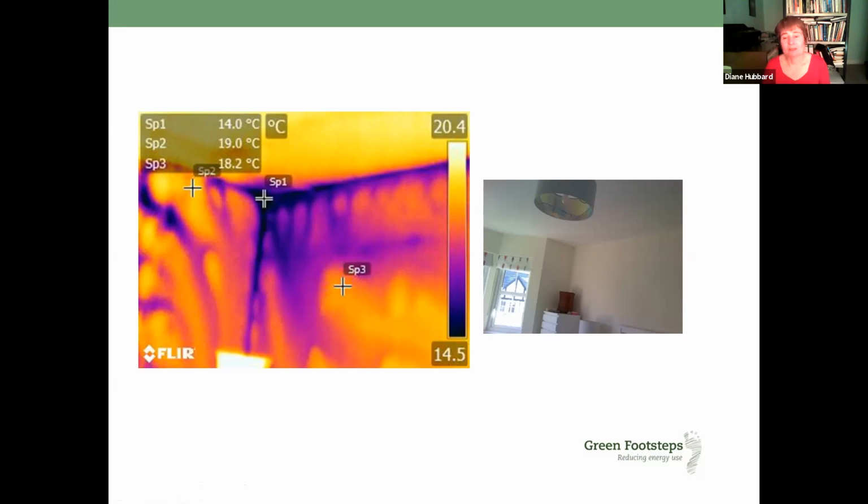And plasterboard should be edge sealed, so around the perimeter of each board as it's fitted, it should be sealed all the way around the edge. Now, it's quite difficult to do when you've got things like plug sockets. But what we can see in this image is what's happening behind it. This image is taken with the building depressurized below outside. It's warm inside, it's cold outside the building.